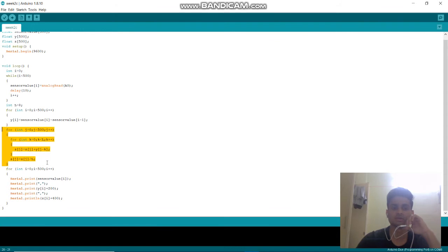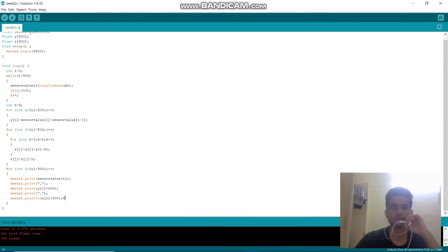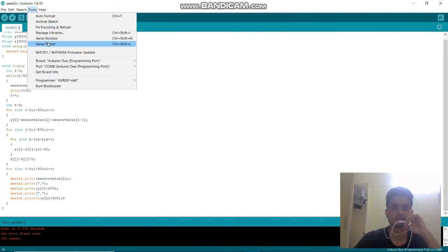If you want to know more in detail about the moving average filter and derivative filter, I'll link the last video in the description. And then we plot everything. We plot the sensor value, that is the input from the sensor. We plot the derivative filter with a 200 vertical shift, and we plot the moving average filter, our final output. So we'll now upload this. So we're done uploading now. So now I'll plot this.